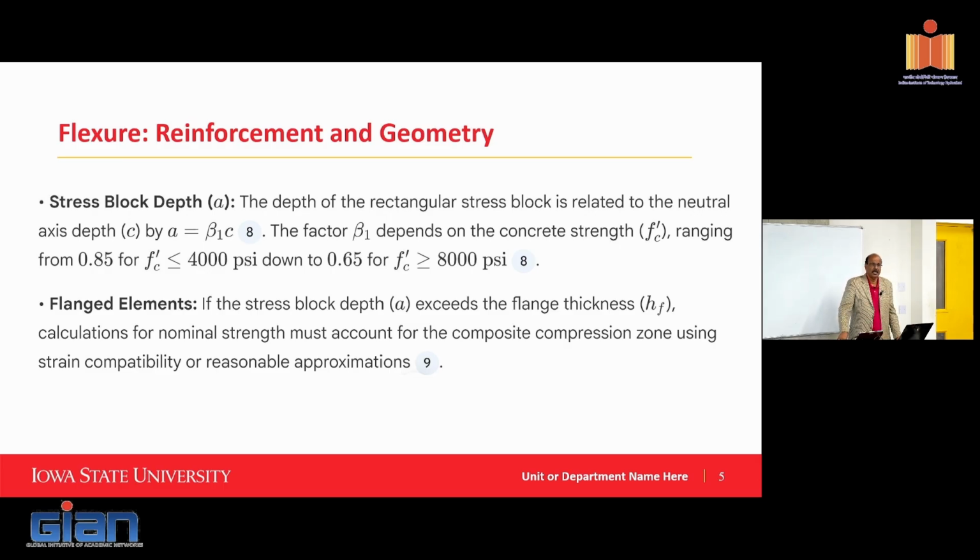So we talked about L-beams and inverted T's. When you have a flanged element, you have to check, when you do the moment calculations, whether the neutral axis is within the flange or is flange plus some part of the web. There's also been some controversy over the years in terms of how the neutral axis depth should be calculated and the stress block should be computed. But again, this is not about doing research. You want to see what's the best knowledge out there, and this guidance will provide you how to compute those things.